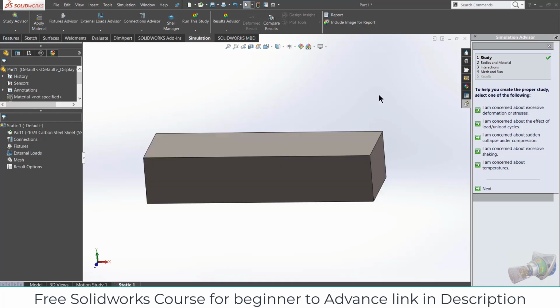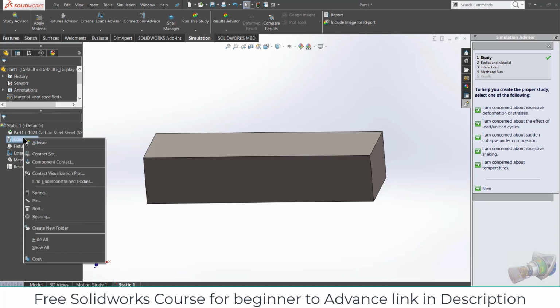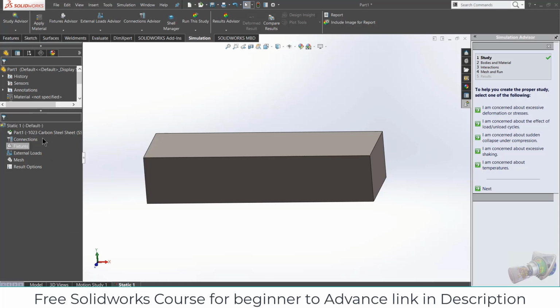Now the second thing I need to define is constraints or connections. If I right click on connections, you can see there is nothing below connections. Basically there is a little arrow you will see. Connections are used when there are more than two parts in your design. In my case it is a single part, so I don't need to define connections. Connections define the relation between two parts. Are they rigid, are they connected, are they bonded with each other?